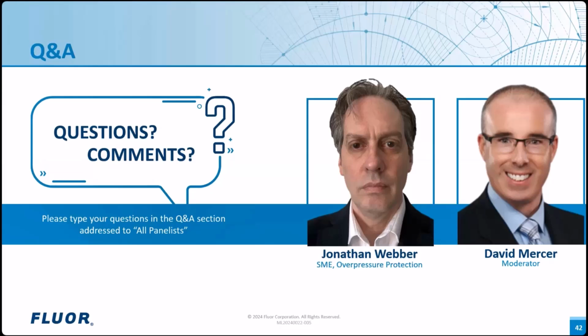Okay, that's a really good question. We have seen it done, yes. However, it's very, very tricky because of the extreme speed of the pressure transients. So yes, it can be done, but there are other alternatives. The first preference is always to try to slow down the speed of the valves closing, or to put some sort of buffer on the pressure, like an expansion tank. And there's also specialty valves designed, like Danfoss valves, specifically designed for surge.